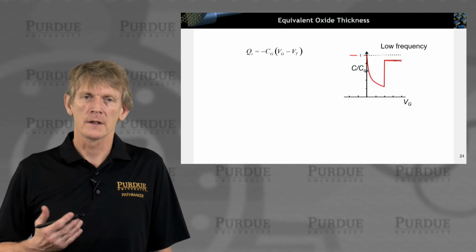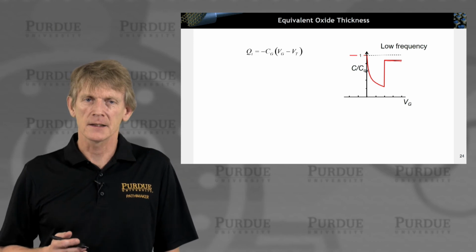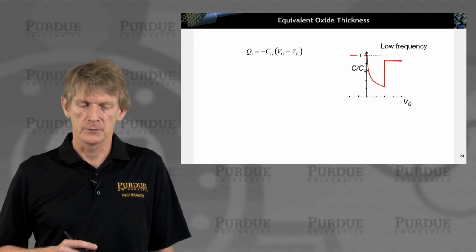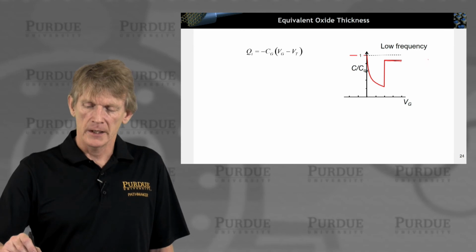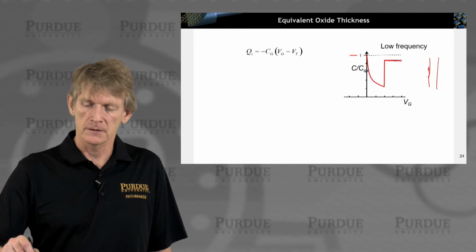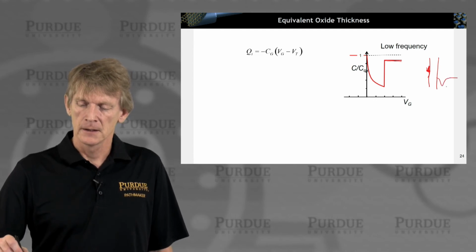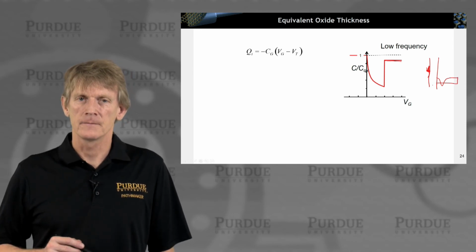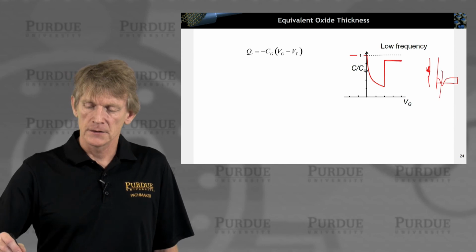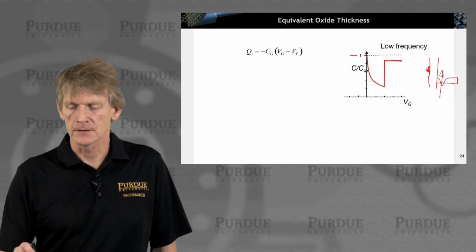And that has to do with the charge being distributed in the semiconductor not exactly at the interface, but in a spatial distribution. So you have charge at the interface in an ideal way here. You have a delta function of positive charge, and you will have sort of a pile of electrons here, and you will have depletion charge on this side. And this charge has a spatial moment, and it's not exactly at zero.